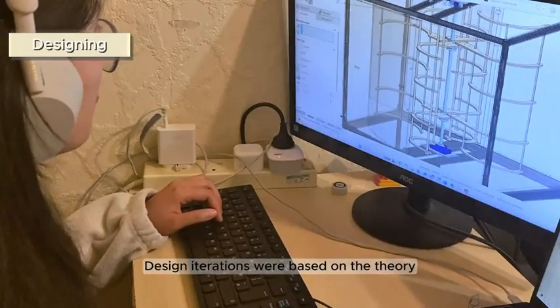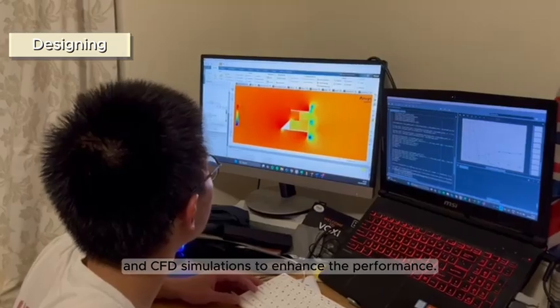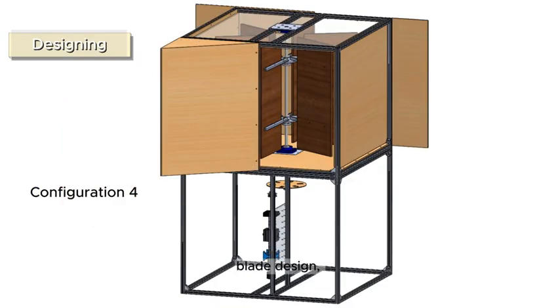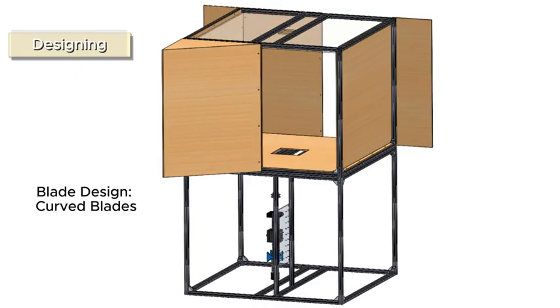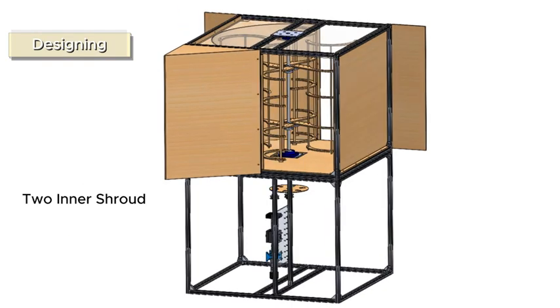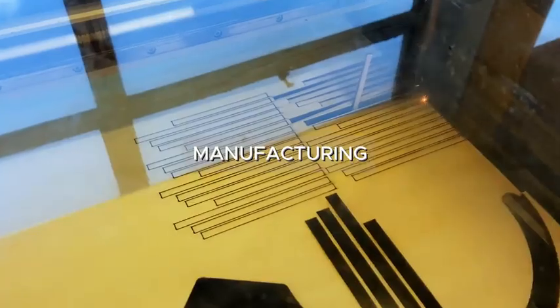Design iterations were based on the theory and CFD simulations to enhance the performance. This included adjustments to model configurations, blade design, inlet length, inner shroud, separator length and wedge design.